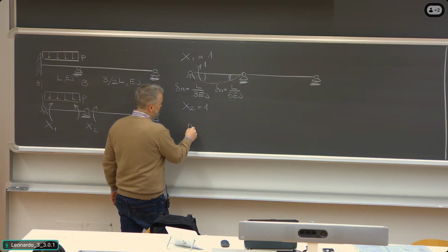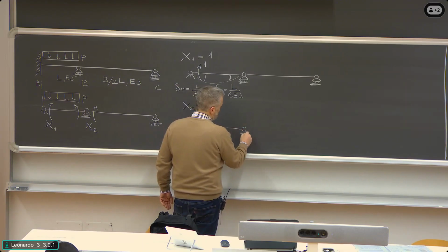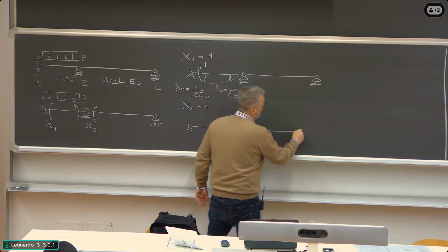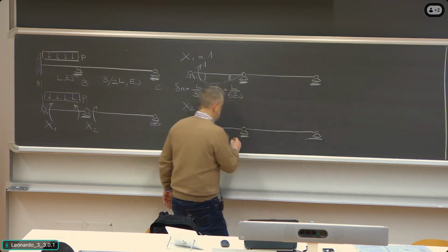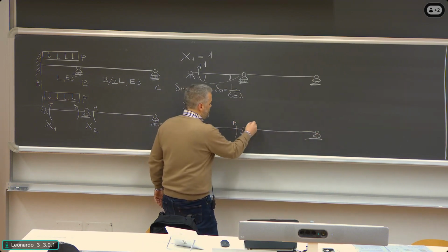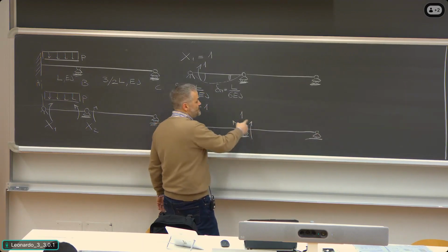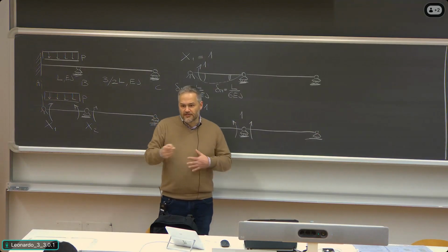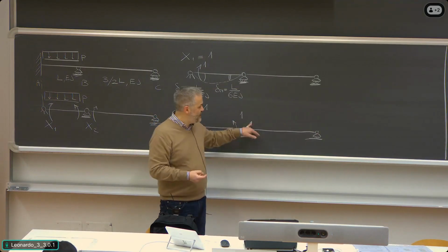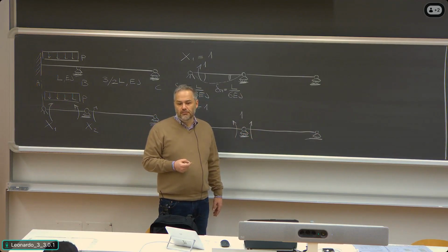Same structure deprived of all the loads, which means distributed load, nothing else. Then you have the bending moment x2, which is now 1, which means 1 on one side and 1 on the other side, not 1/2 and 1/2. Both are 1, to make the principle of action and reaction fulfilled.